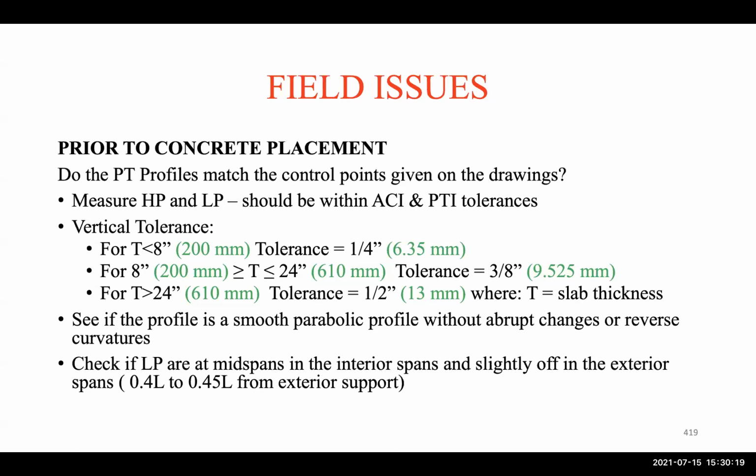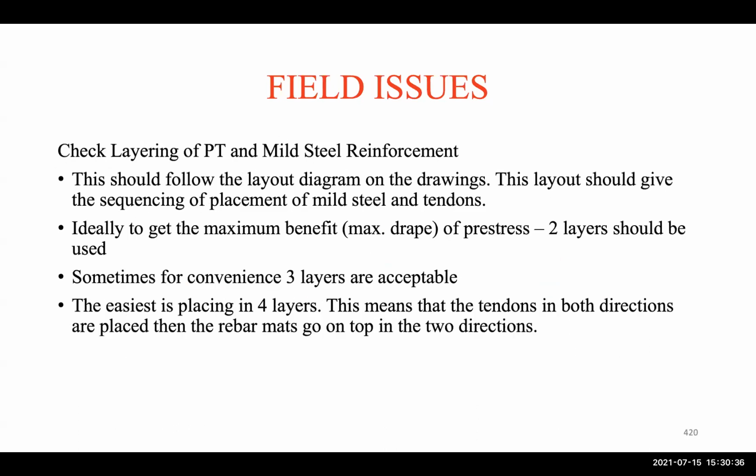But in PT, this is like reinforcement. Everything is done. The cables are thrown on the formwork, and then the post-tensioning is done after we cast the concrete. So we have to make sure that things are in place, so when we apply the PT force, everything is in place.